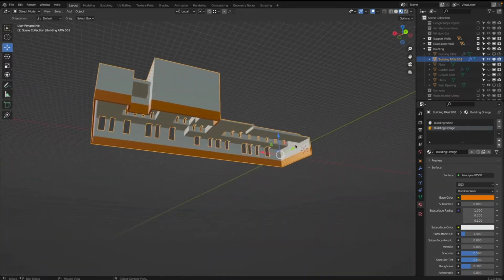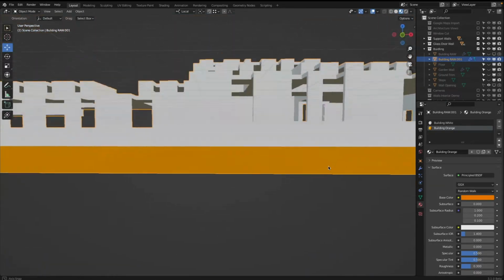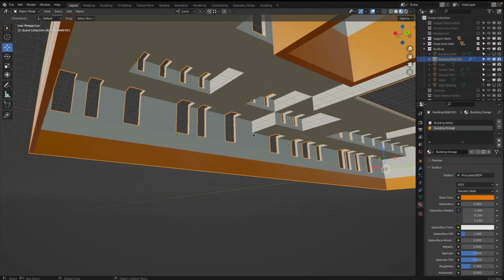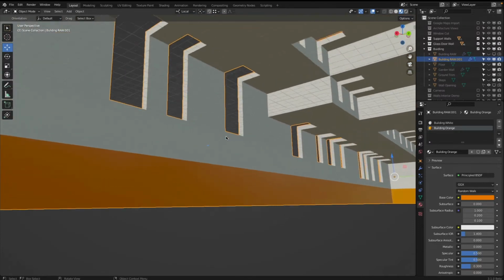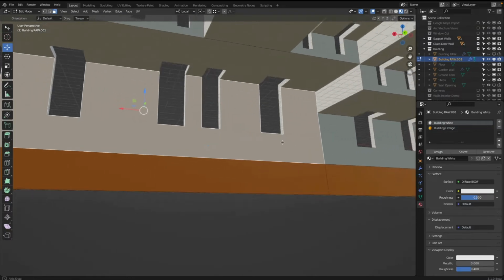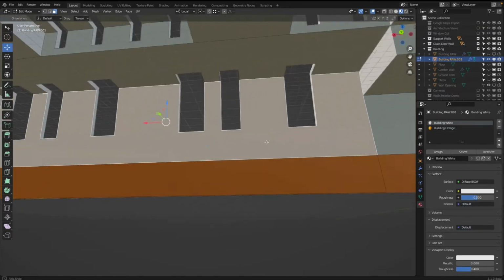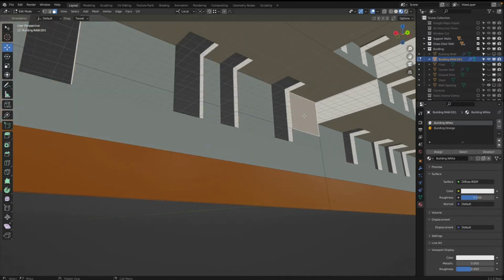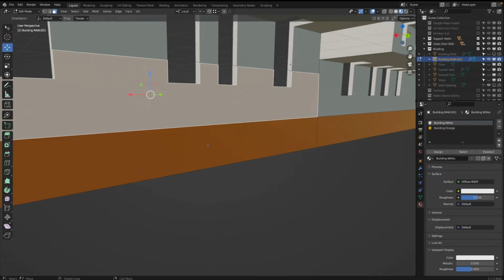There we are. So how can we now make the material go through the inside here and maybe stop at this wall? And then we have a little bit also in here. So there is my piece now. So I have this face selected. I can press K, click here, and then X till there, click Enter, and that's it. So you see this face I sliced.